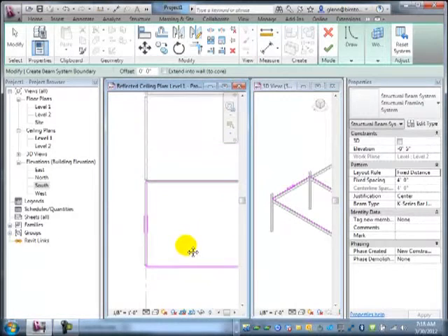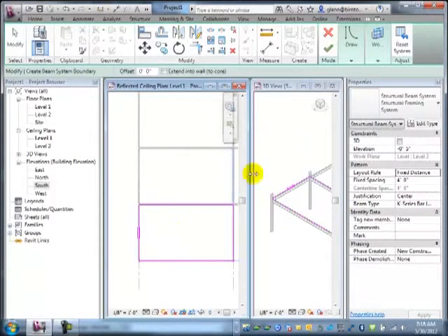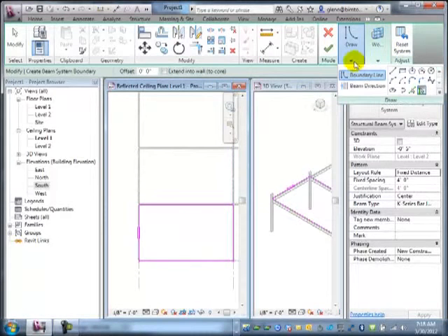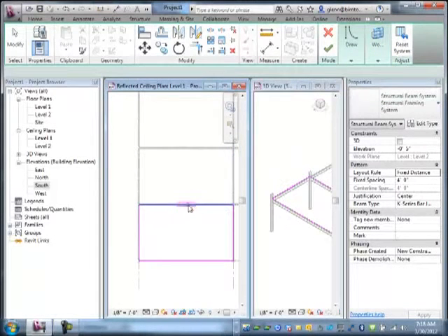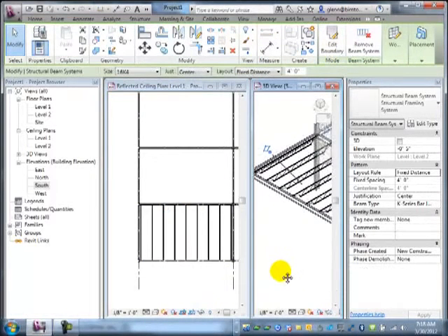Let's see if we can get that to happen in Revit Structure. I know in Revit Architecture it's not doing that, but let's see on both sides. So over here, if I change the beam direction this way, that'll switch the beam joists to go that way. If I do this side, it'll go that way. But when you finish, you basically get something like this.